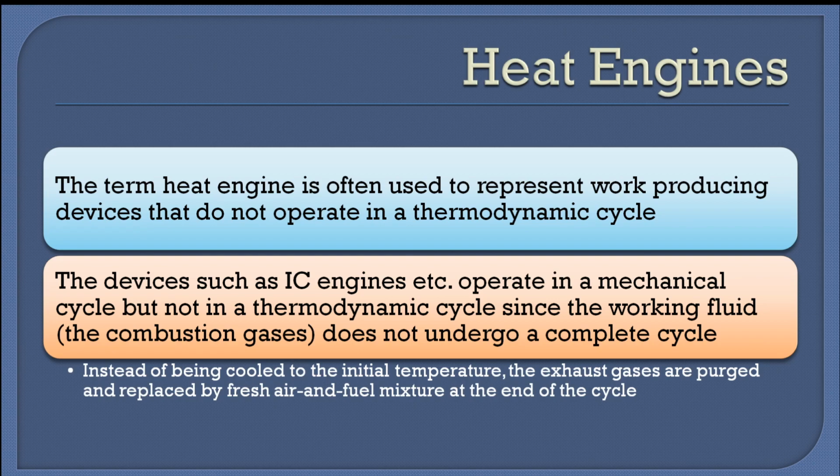In the case of a mechanical cycle, the working fluid is given into the first component of the system. It will undergo certain processes and come back to the initial condition, but there it will be expelled out of the engine, and fresh working fluid will be given in the first process again. For example, in an internal combustion engine, the exhaust gases, instead of being cooled to the initial temperature, will be purged out and replaced by a fresh air-fuel mixture.